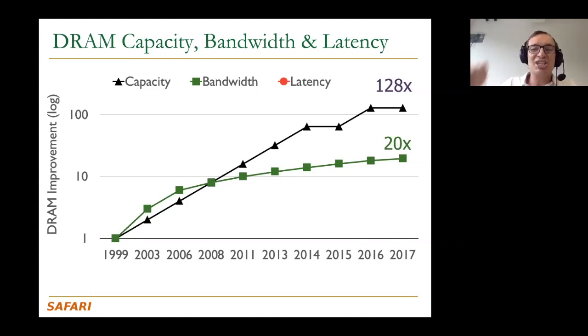They actually etch the chip a lot in a 3-dimensional fashion such that they can put the capacitor inside there. So if you look at the aspect ratio, for example, of a capacitor and access transistor, in the third dimension, the Z dimension, the capacitor is about 70 to 90x longer compared to the access transistor, which is really interesting to me, actually.